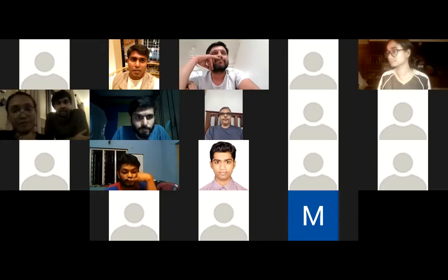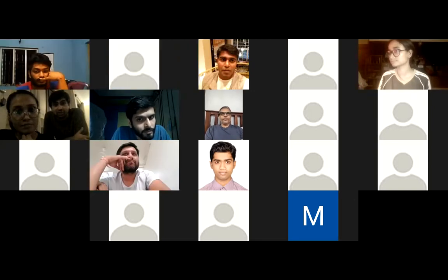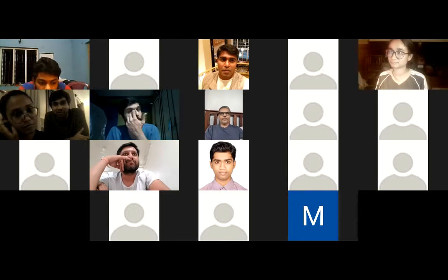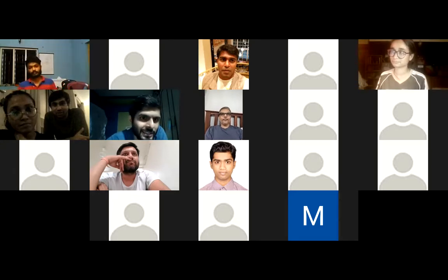Okay, I have two. One quick thing for the guys who are doing this, especially Prem, Negi, everyone. Just make sure your pipes, especially for the sieves, are fine. Double check, triple check your connections. Make sure your gluing is perfect. You're playing with a lot of pressure over there. 2 to 3 bars, sometimes 4 bar pressure.